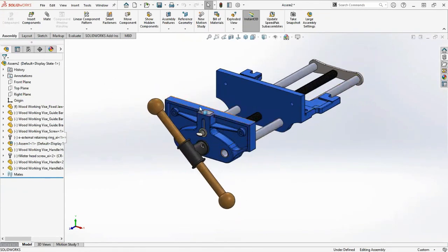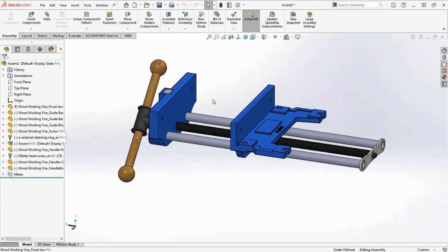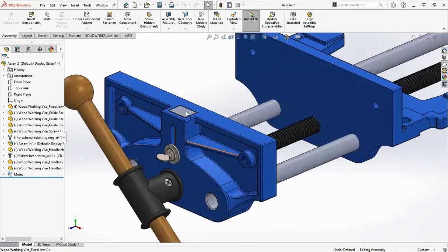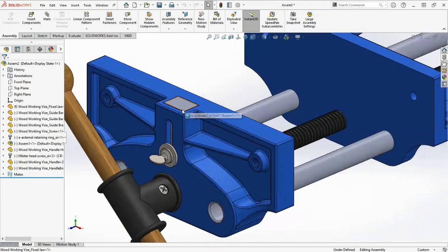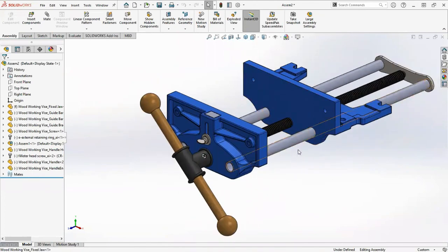So I think that about covers it for our session from advanced part modeling to assembly making. Highlights are that when you create assemblies, use in-context modeling as much as possible to help save you time. For example, that vise dog was created pretty quickly and easily without having to refer to any dimensions. And try to assemble your components just as you would in real life and apply the mates as those components would relate to each other in real life, so you can test it as